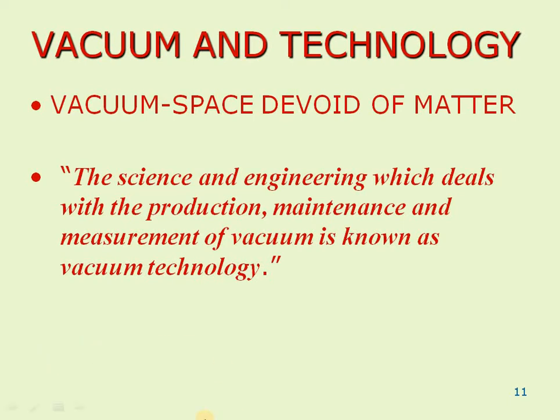You can define vacuum technology as a branch of science or engineering which deals with the production, maintenance, and measurement of vacuum. So it involves vacuum production, how it is produced, the machinery, different pumps, and subsequently you have to maintain that pressure. That's also very important.